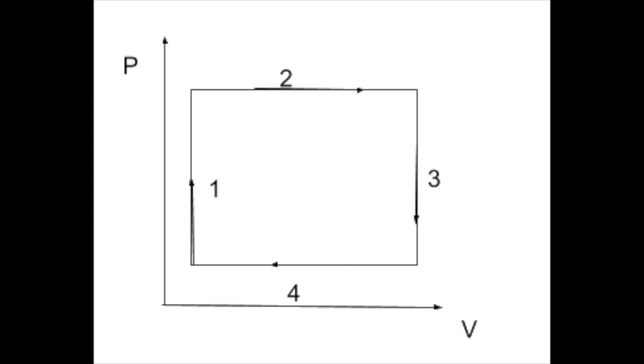Using pressure equals force over area, we can then use Newton's second law and rearrange the sum of forces equation, which is weight minus pressure times area equals 0, or in other words, the force experienced by the piston due to the pressure equals its weight. Using this, we can then derive that the second pressure at state 2 is the weight of the piston divided by the area of the piston plus the initial pressure. In this case, we will assume that the acceleration of the piston is 0, since testing with the piston and metal cylinder indicated a very steady rate of rising visually.